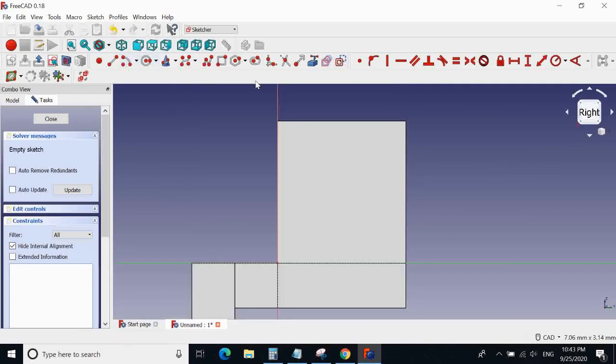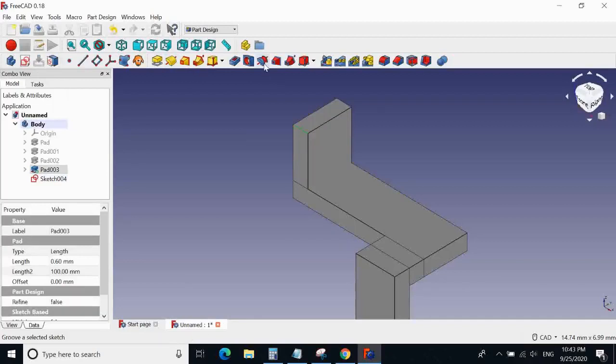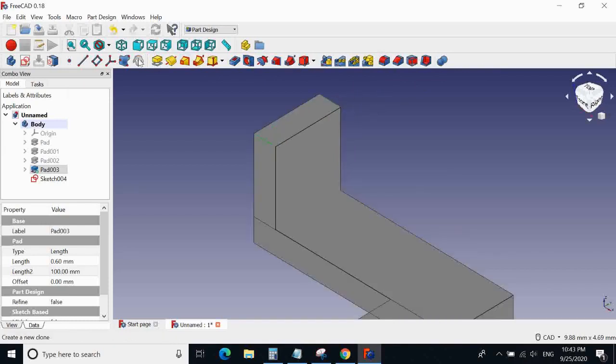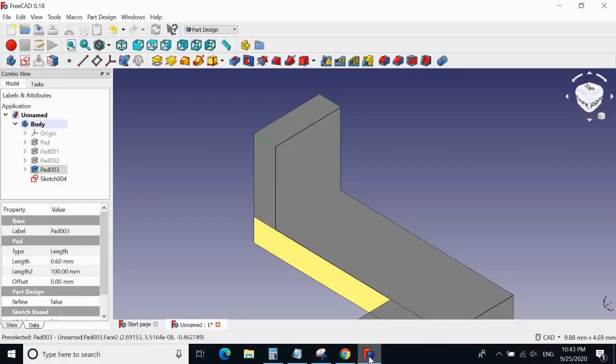Now we should be able to do a constraint. Okay, actually better yet, let's do a chamfer. Chamfer, yeah, that's what it's called. Yeah, rounded. Make a fillet rather. Okay, fillet. Select these 2 edges. There are 2 ways you can go about making these semicircular things. You can round them off, or you can cut them off. Basically, this will round them off.